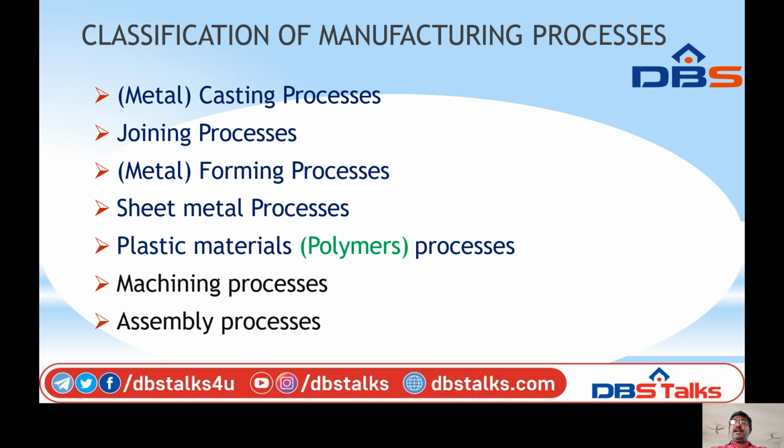The next one, joining process. The joining process includes welding, brazing, soldering, mechanical fastenings, etc. Mechanical fastenings can be used to provide either temporary or permanent joints. The third one is the metal forming process. It involves forming and cutting operations performed on metal sheets, strips and coils.